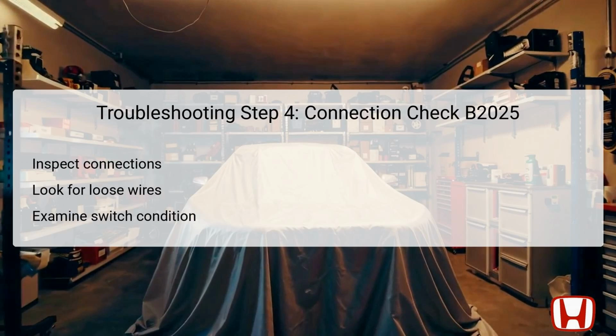If DTC B2025 continues to appear, it's essential to check for physical issues with connections. This involves inspecting the wiring between the power sliding door switch and the control unit. Loose connections or poor wiring can lead to intermittent faults, spawning the B2025 code. Ensure that the condition of the switch itself is intact. Any visible damage can affect performance.